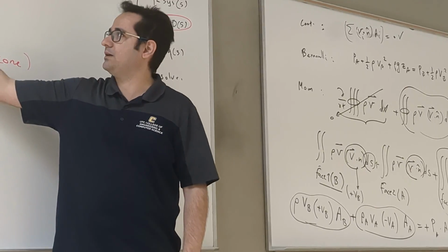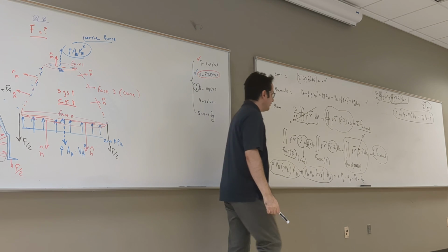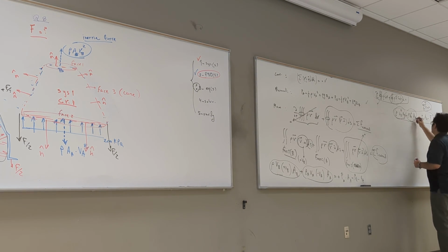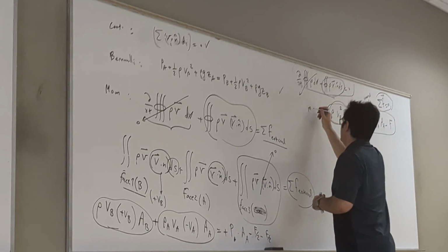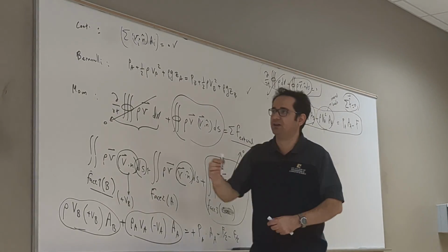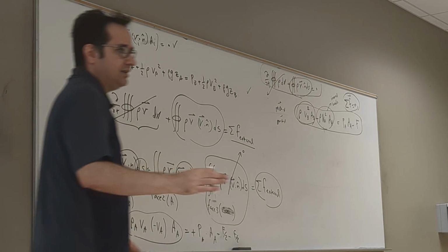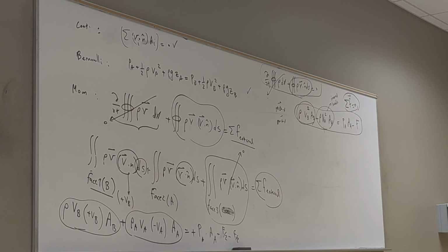But the way they do that, they also put the inertial load on the FBD, you see this is dashed. These are the dashed loads, the inertial loads. Just like dynamics. In dynamics, it was MA, acceleration in X, MA, acceleration in Y. You would put acceleration on your FBD with dashes. If you haven't done that, that's a big, serious mistake. You really need to go back and redo the entire dynamics. You have to put your acceleration on the FBD.